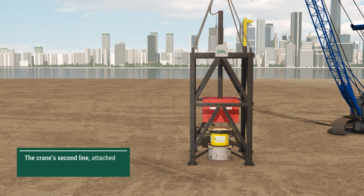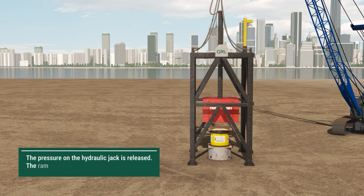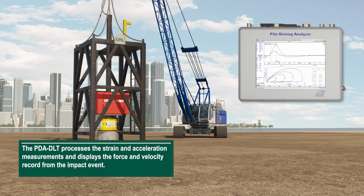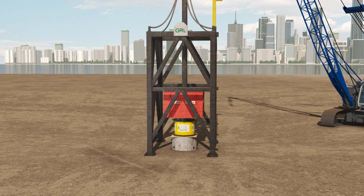The crane's second line, attached to the guide frame, is also lowered. The pressure on the hydraulic jack is released, allowing the ram to fall and impact the top transducer. The PDA DLT processes the strain and acceleration measurements and displays the force and velocity record from the impact event. The foundation movement from the blow is measured and recorded.